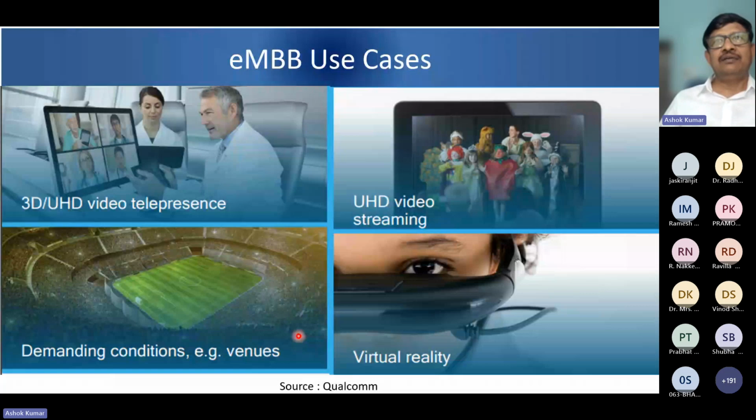small cell because it covers lesser distance, maybe 10 meter, 20 meter, 30 meter kind of. So I can deploy 10, 15, 20 small cells in such a stadium on millimeter wave. And in millimeter wave, as I said, operators have quite a chunk of spectrum, 1000 megahertz. And in 5G, we support a channel bandwidth of 400 megahertz, and I can deploy even a multi-carrier environment.